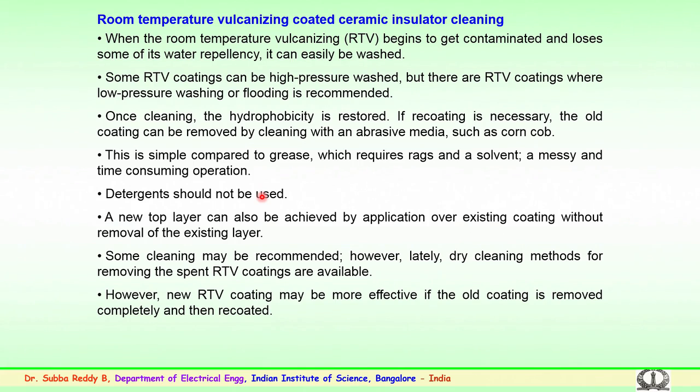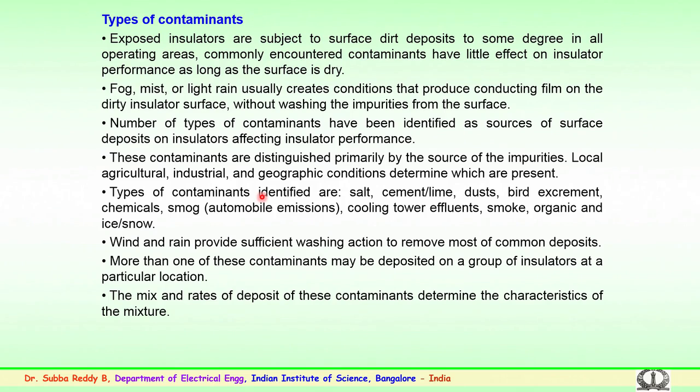However, lately dry cleaning methods for removing spent RTV coatings are also commercially available and normally practiced. However, new RTV coatings may be more effective if the old coating is removed completely and then recoated. This decision has to be properly taken by the utilities.